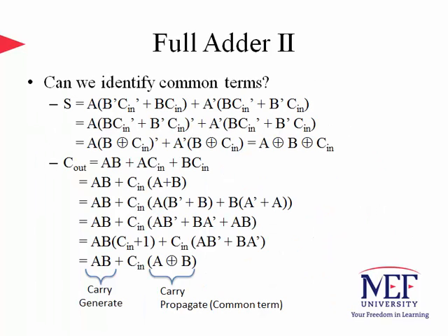As always, the next thing we do is to identify the common terms, if there are any, as we have seen in our combinational circuit design class. Previous lectures have a lot of examples explaining that. Let us use parentheses to group terms for S and recognize that the terms inside the parentheses can be implemented by either using XOR or XNOR gates.